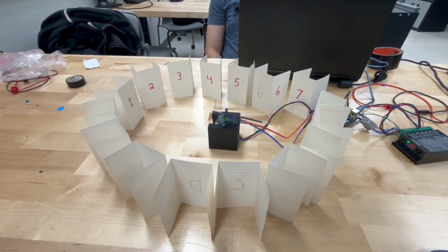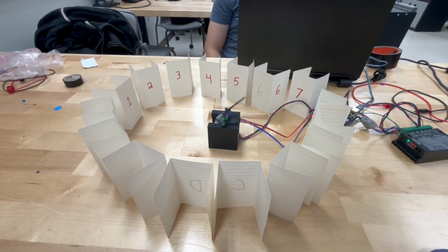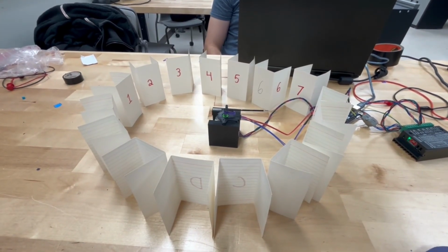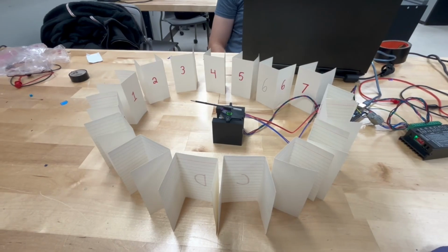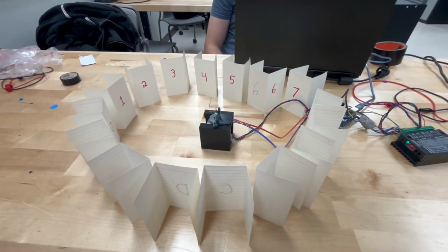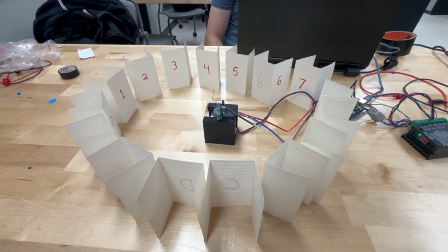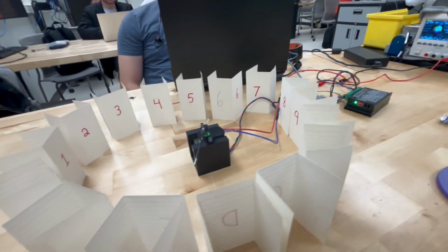3. Optical or magnetic sensing. Optical: an LED shines light through the encoder disk. A photodetector senses light/dark transitions. Magnetic uses a magnetized wheel and Hall effect or magnetoresistive sensors. This converts rotation into a raw analog or digital signal, typically square wave pulses.